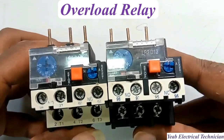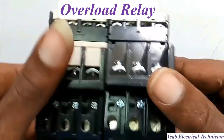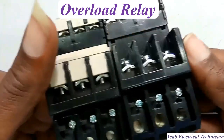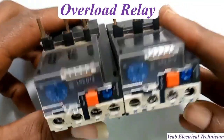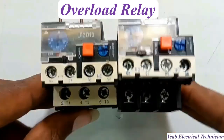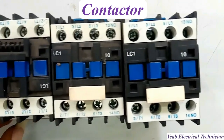When a prolonged overload is detected, it sends a signal to the contactor, which then opens the main power circuit, stopping the motor. Overload relays can also detect or protect against other dangerous conditions such as a three-phase motor losing one of its phases.